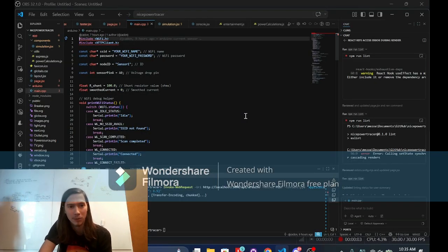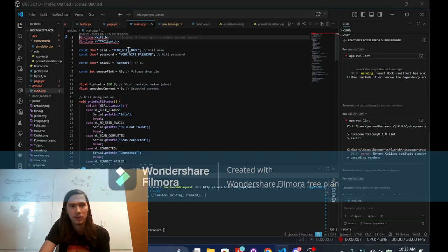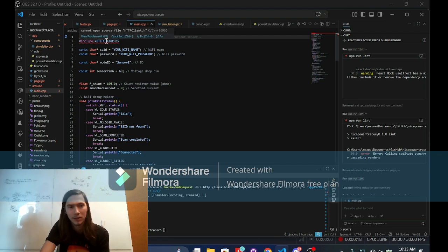All right, here is the code behind our ESP32 Arduino. First, we tried at first to use WebSockets, but we learned that when we deployed our app fully, Vercel does not allow live WebSockets. So we instead turned to an HTTP POST request to send our current data.